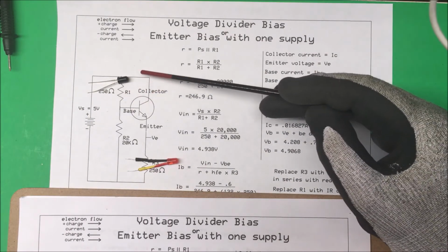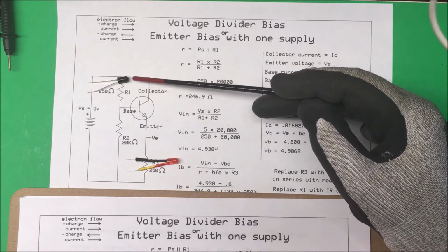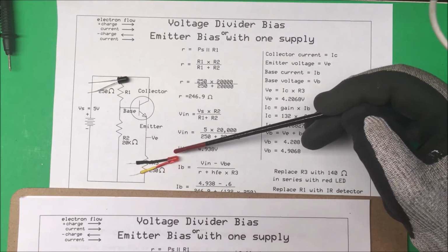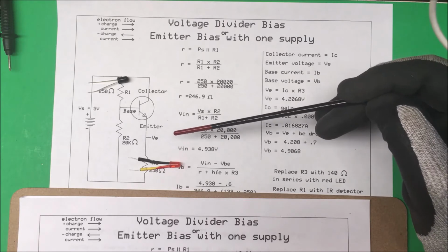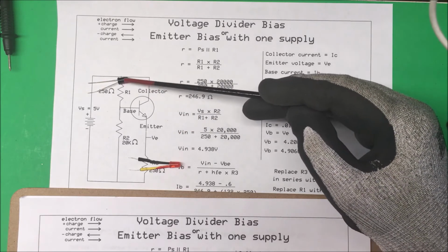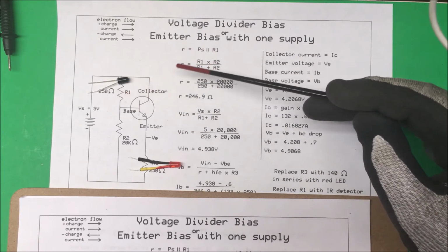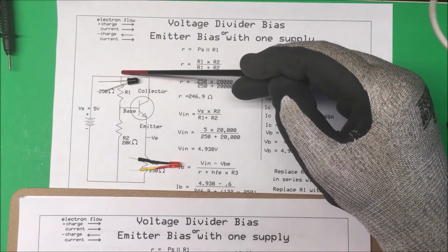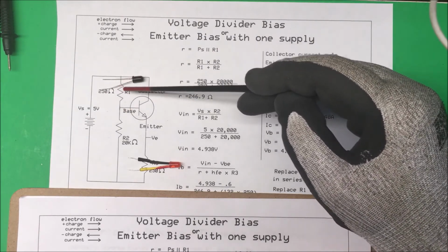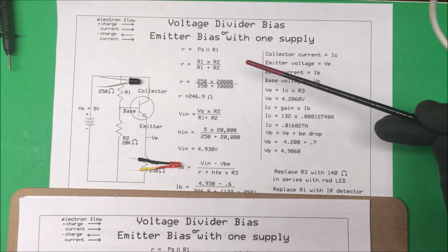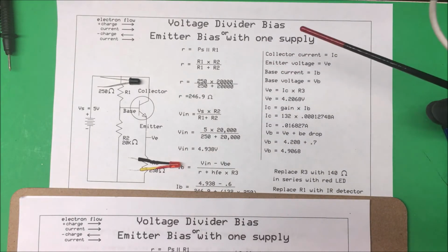And then when we shine infrared light in here, it should turn on the LED down here. Okay. So now you have to reverse bias these. So you have to put the negative up here and the positive down here. That's how these infrared detectors work. So I'm going to put that together, and we'll see if that works.